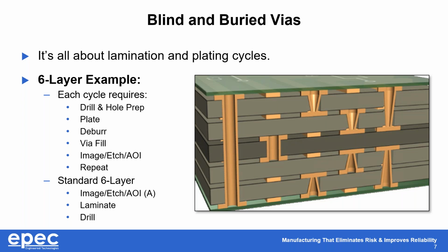And we're just controlled depth laser drilling the blind vias, and we're taking out the whole two other lamination cycles. So when you're talking about the difference between being able to deliver in 3 days and 7 days, that is really a big part of what could be the determining factor. So really working with your fabricator early on, talking about what you're trying to get accomplished, can help us ensure that we can deliver a lot faster.